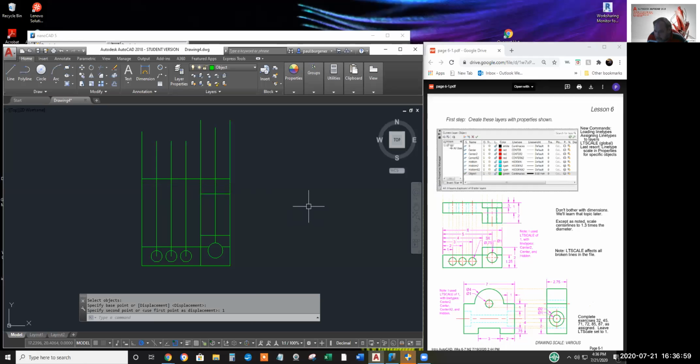And I'll copy, copy, not move it 1 unit up. I need a line straight across here. So I'll copy, where's copy? Copy it. Again, 0.5 unit up. And I'll trim away the garbage. And erase that guy.